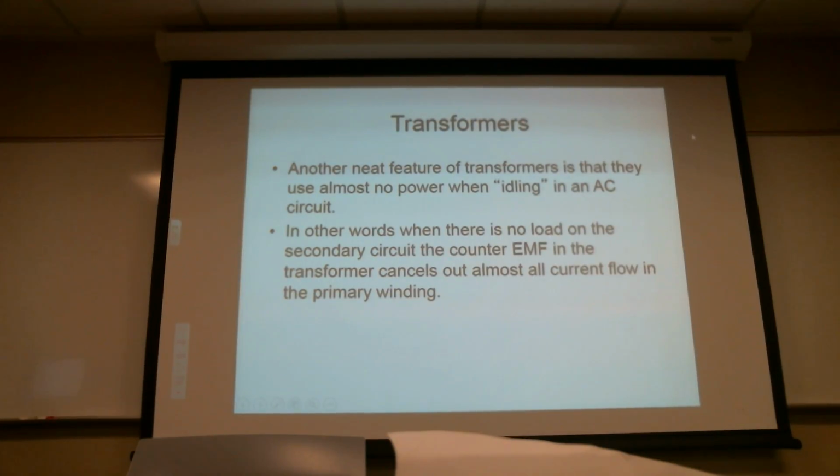New world technology, the kinds that typically use a digital circuit. The transformer comes in, rectifies to DC, and then all conversion is done there. You'll find those are much lighter, and they don't weigh all that much. They have very little copper in them compared to a standard transformer.